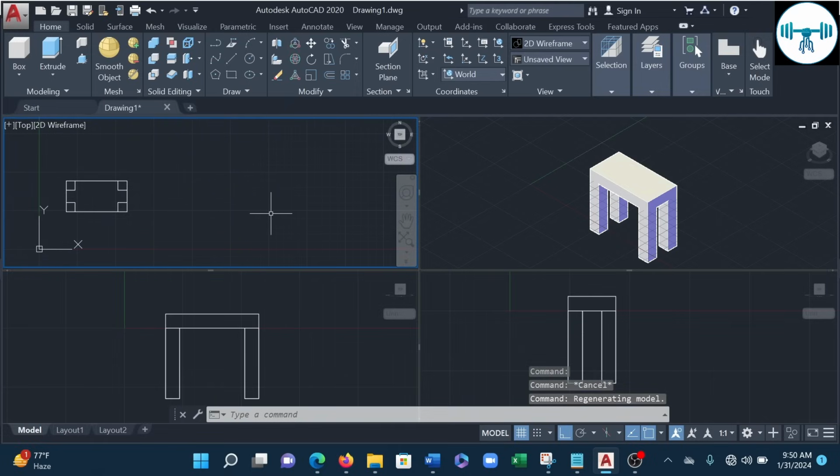Subsequently, we are still going to deal with more complex shapes, but let's move on to loft right now. Now we use the loft. Okay, we use the loft when we want to draw objects that have circular cross profiles, circular cross sections, but with different diameters. So when an object has circular cross sections but circles of different diameter make up the cross section, then loft is likely the tool you may want to use to draw such an object.